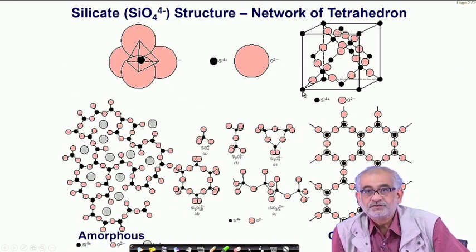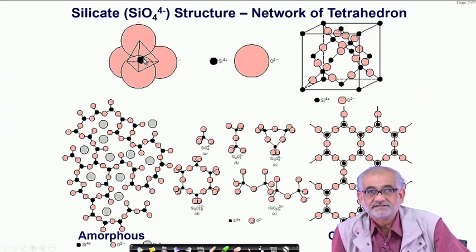Now we are moving into non-crystallinity. So, for example, you imagine that now we have a silicate tetrahedra, simply a tetrahedron where I have a smaller species in the middle and 4 bigger around. If this is a single unit, I can actually pack this unit in 2 possible ways.